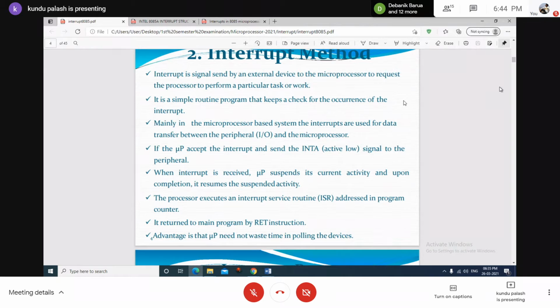Upon completing the tasks under the interrupt service routine, when it encounters the IRET instruction, which means the end of the interrupt service program, it immediately branches to the location where it had been interrupted. It is just like a subroutine call. That's why the stack pointer operates in a similar manner as it is observed when calling a subroutine.